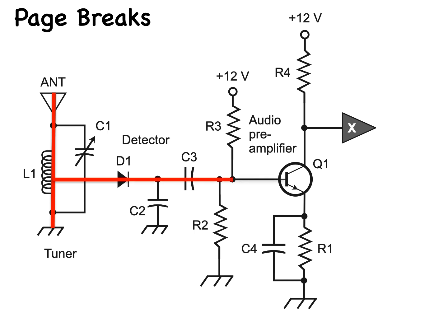Capacitor C3 passes the AF part of that signal along to the base of transistor Q1. Capacitor C2 shunts the RF portion of the diode's output to ground because the circuit doesn't need the RF energy anymore, and its presence would only cause trouble. Transistor Q1 acts as an amplifier for the extremely weak AF signal at its base. Resistors R1, R2, R3, and R4 ensure that Q1 gets optimum DC voltage, called bias, so that it will produce the greatest possible amount of amplification.